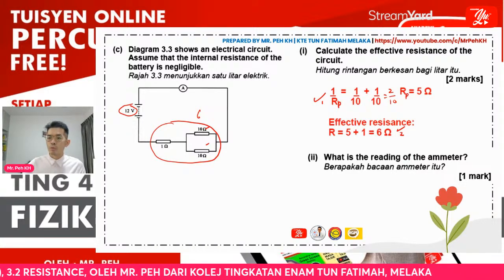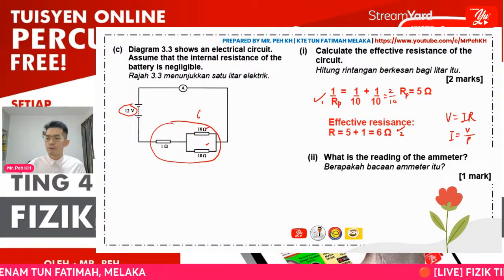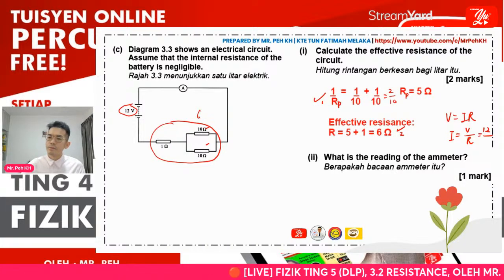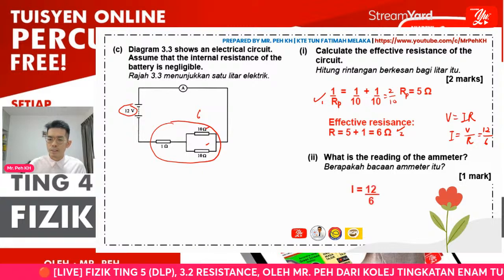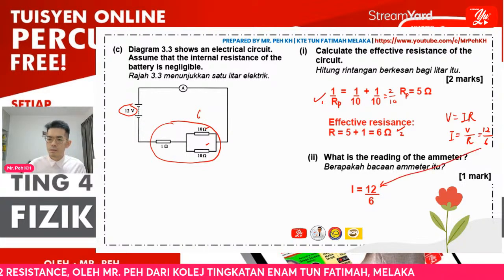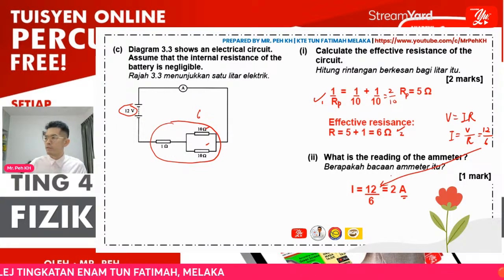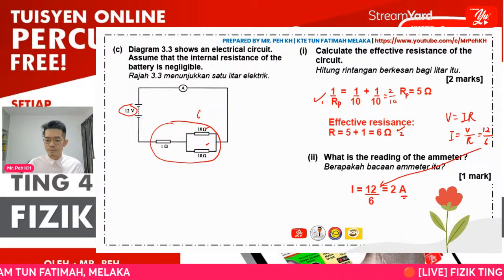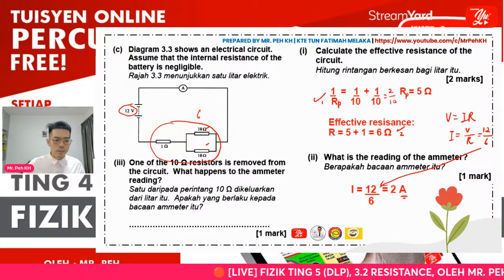Here we use Ohm's law, V equals IR, so I will be V over R. V is 12 and R is 6. So the step will be 12 over 6, and then we get 2 ampere. Make sure you give the unit for the answer. Then the next question is like this.